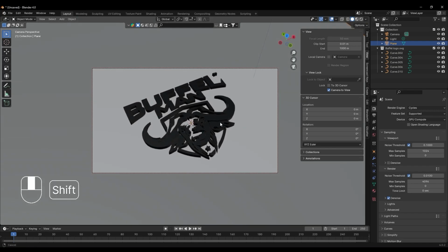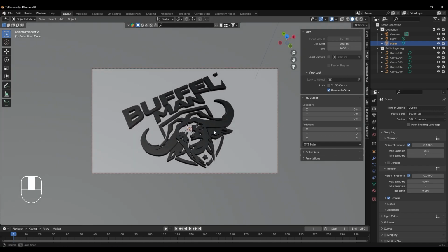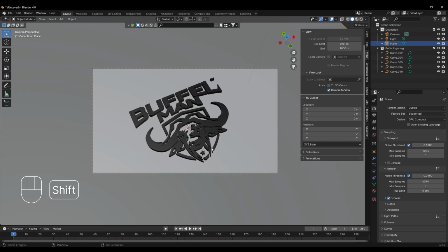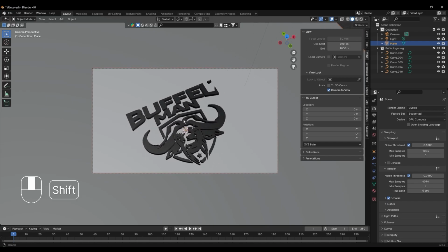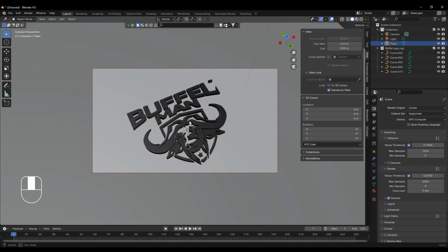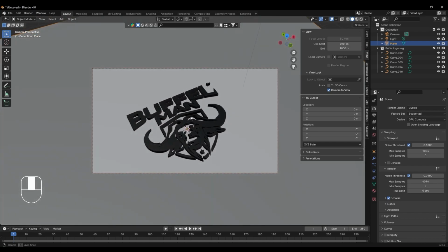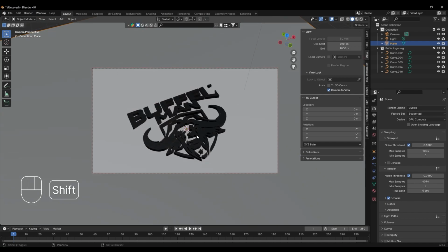So I'm going to go for just a side angle, a little bit offset, and maybe just zoom out slightly. All right. Now, if you're wondering how to move around, you can hold Shift and middle mouse button and you can move around like that, or you can just use middle mouse button to rotate, just like that. So that's the view I'm going with. I like that.